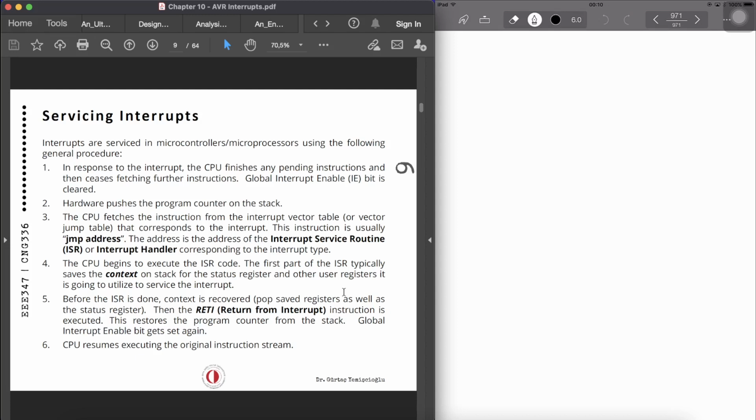When we are using interrupts, subroutines generally can get into another subroutine before it returns from the call. Now, the subroutines that are shared between the interrupt routines and the other programs running on the microcontroller need to be re-entrant. So what is re-entrant?